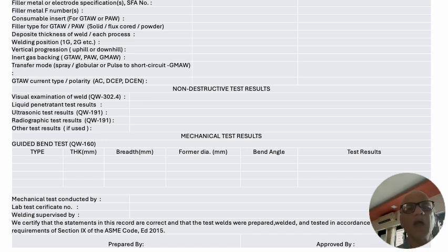And even if we have a practice, there is no substitute for a mock-up. The cost of repair on the actual job and the delays associated with it, and if it is under a third party, getting their approvals and permissions and dealing with their doubts, it's so tedious. I think we can easily afford to bring a small mock-up and get it welded. Even if there is a delay of 1 or 2 days, I am sure you will be saving weeks and months, and a huge cost in case it gets into trouble. So prevention is surely far better in welding, as rework is very expensive.